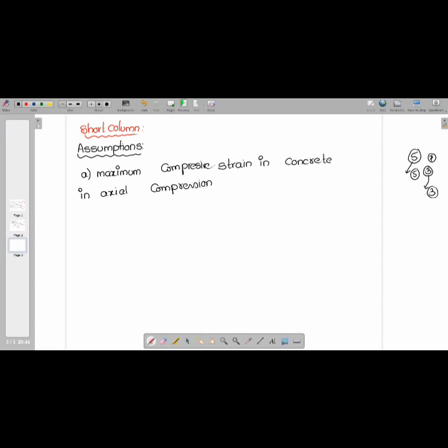Very good, Asima. Sir, if you remember, here it is 0.02, and here it is 0.0035. If you take 0.0035, you are allowing maximum strain, and that is for the LSM method. For the working stress method, you will not allow more strain, you will allow lesser strain, that is 0.002.